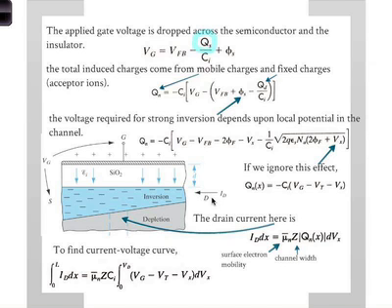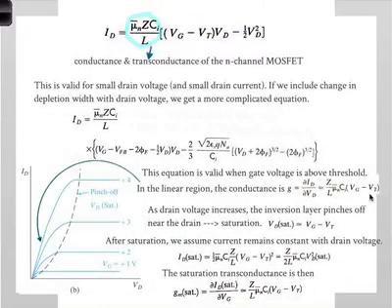That's the point when the pinch-off happens. Of course, it will happen first at the drain, because that's where the biggest depletion region is. The depletion eats into the inversion layer. So we can calculate very easily that the saturation happens when the drain voltage is equal to Vg minus Vt. Barely inverted, also barely saturated. That's the onset of saturation.